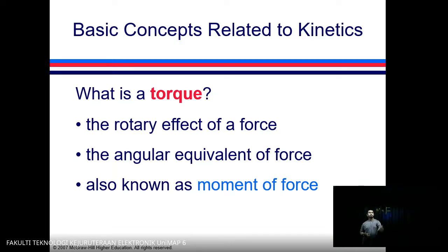equals force times perpendicular distance. Torque is also the same thing. Torque, T, torsion, force times perpendicular distance. So moment and torque use the same equations and the same unit. Force in Newton, D in meter, so Newton meter.